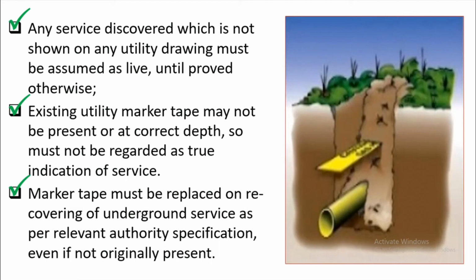So when you expose underground utility services and you want to backfill again after your job is completed, make sure that you replace the tape marker at that location, and even if there is no tape marker that you found during the excavation, you need to provide a tape marker as per the specification of the utility firm.